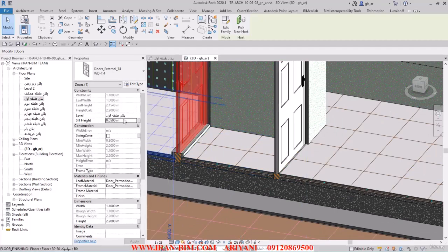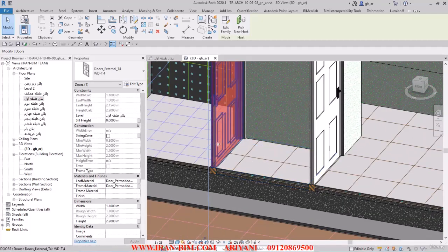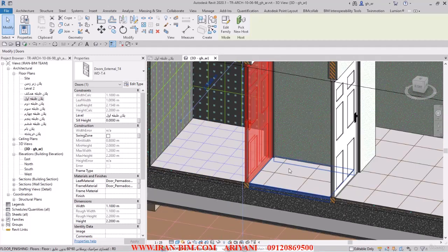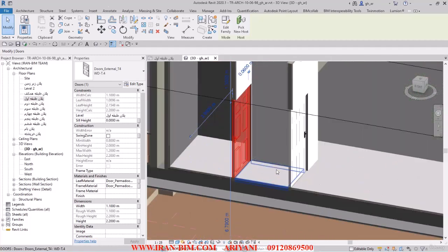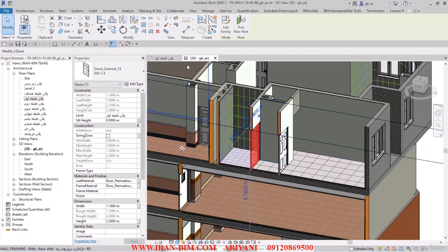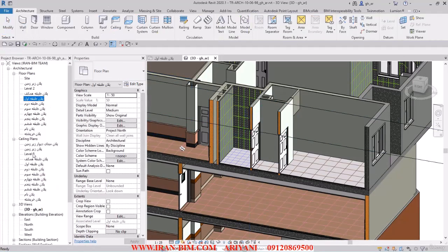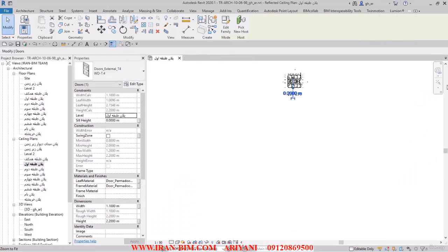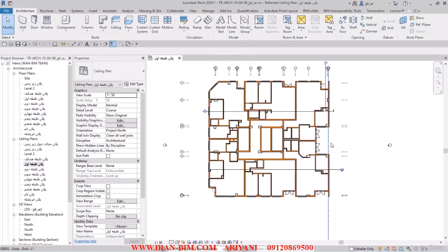We'll do them all in the end, so we make sure we get all of them. Let's just move this down a bit. And the reasoning for this is because this is a bathroom and the water is going to be running here. So I go to the ceiling plans and then the first floor, and I'll be covering the suspended ceiling for this part in the next video.